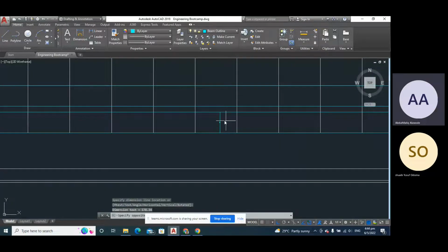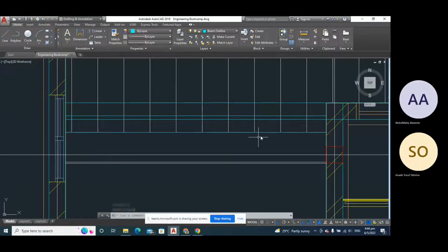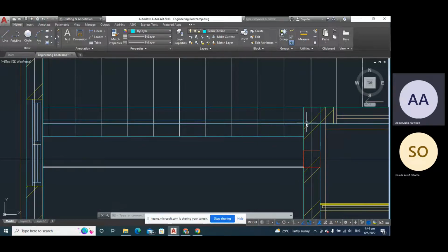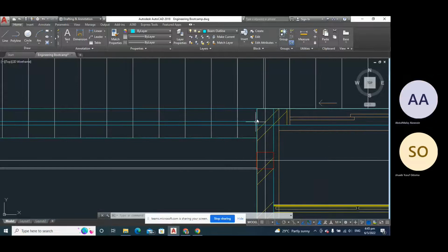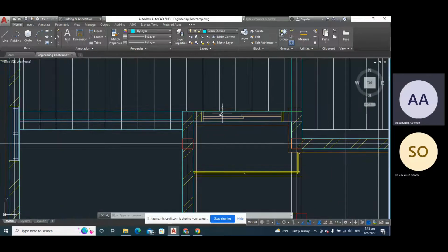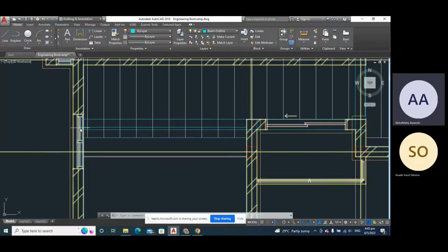This is just like 180 shifting. Obviously they might agree, but if the architect is the adamant type, we will just create another beam here. So here on this beam, you are going to have an eccentricity. This beam coming from here will stop here, then you have another beam that will start from here and end here.